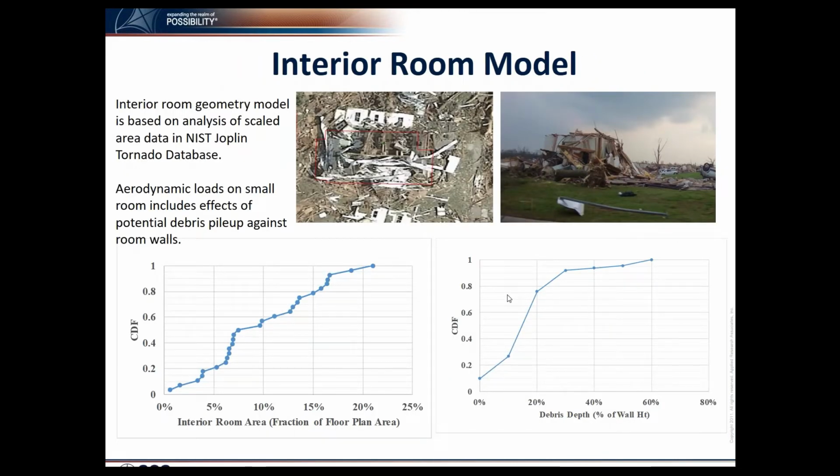We also developed a simple interior room model. This is based on the data that we received from NIST for the Joplin study, where we create interior room dimension based on the footprint of the area. There is the CDF plot of that. And also we developed a debris height on the interior room when only the interior room is present and the exterior wall collapsed, because the debris height plays a significant role on the aerodynamic load of the interior room.